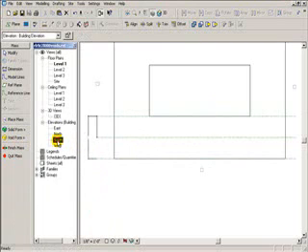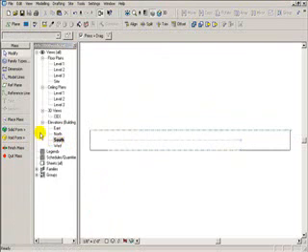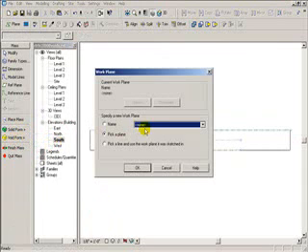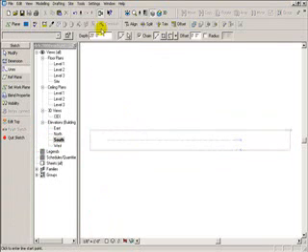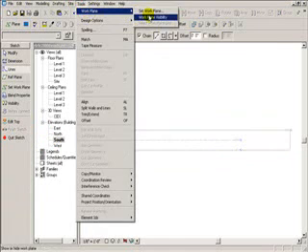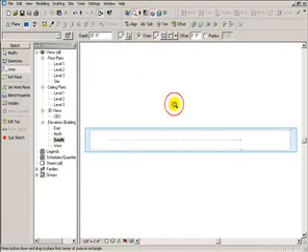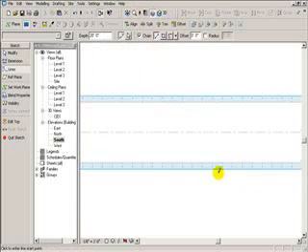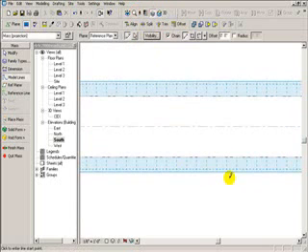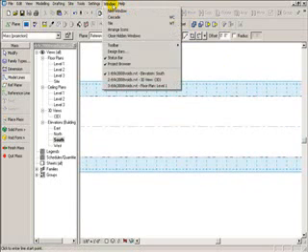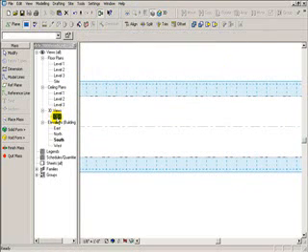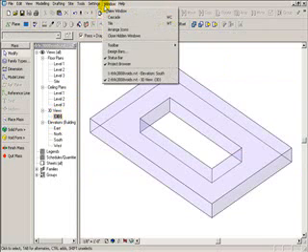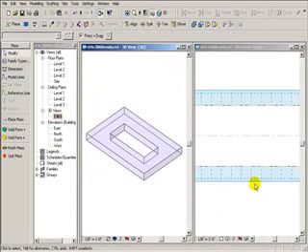I'm now going to switch to my south elevation, and I'm going to go void form, void blend. I'm going to pick a work plane, and I want to start with the interior south work plane. I'm going to turn on work plane visibility. And then I'm just going to zoom in on an area. I'm now actually going to close all windows except for what I have open and open up a 3D view. And then I'm going to tile these so we can see what I'm doing a little better.